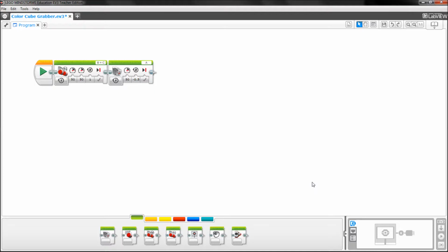Connect your USB cable back to your robot. Download your program. Disconnect your cable and test your program. Now, make sure your program is highlighted on your robot controller. Once you connect and click on the program's name, you should see program underneath, and then run your program to make sure it runs correctly. Okay, that worked perfectly. The arm came right around the cube.